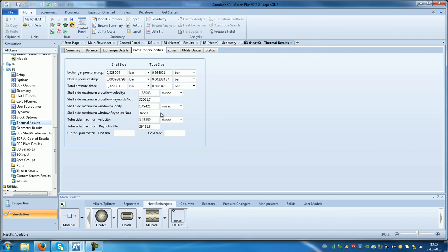One thing that is important, you don't want to have the pressure drop on your nozzles, you want to have the pressure drop over your heat exchanger. So if you have only pressure drop over the nozzles, this is wrong, because you want pressure drop over the heat exchanger, because there the heat exchange takes part, and not in the nozzles, because the nozzles are the inlet connections of the heat exchanger. So if you make them very small, you can get very high pressure drop, but you won't get a really good heat exchanger. So that's something to keep in mind.